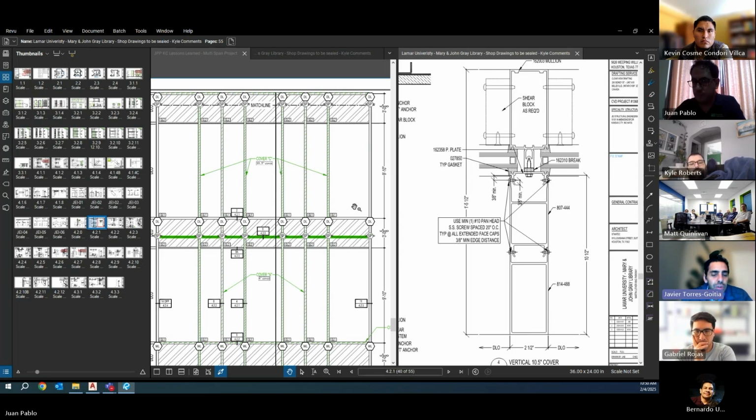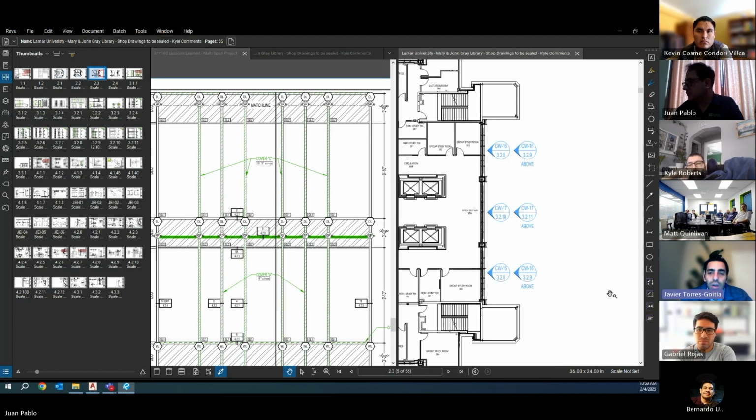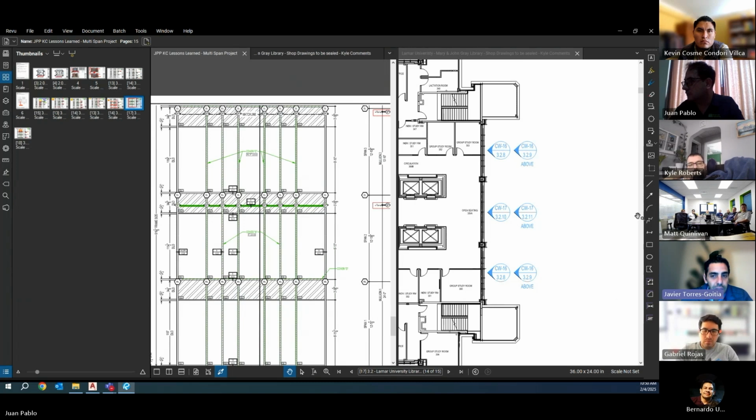If you look at the floor plan on the left screen, Juan Pablo, the corners of that building offer what Stuart called a wind shadowing opportunity for us to shield those frames and not apply the full corner zone or even zone 4 wind load. On the screen on the right, we would be considering wind going in the up and down direction.